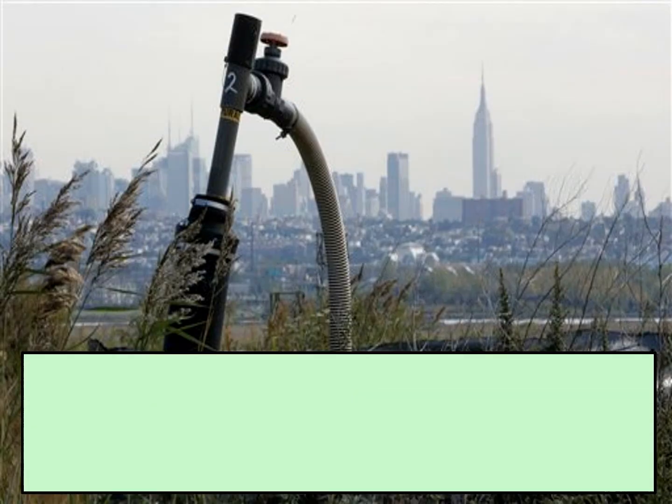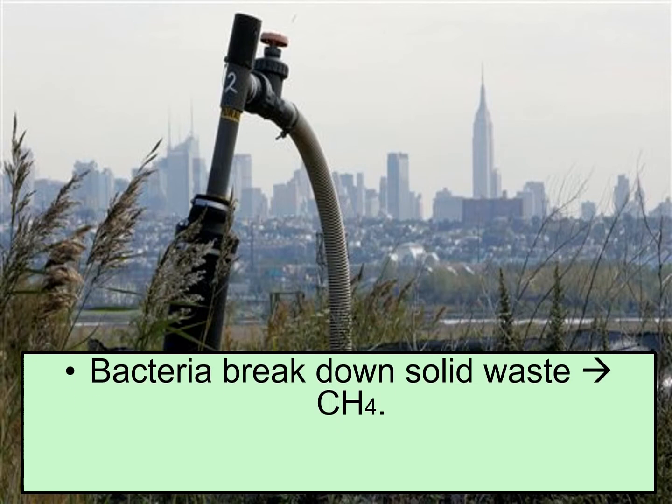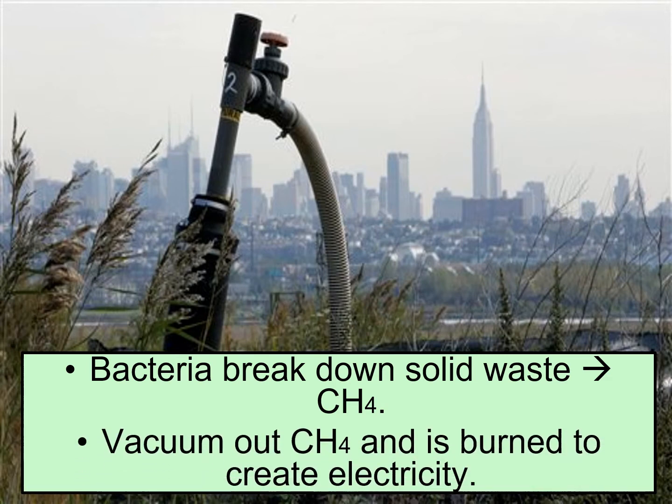A cool thing about sanitary landfills is the bacteria that are in that soil can actually assist in the decomposition of the solid waste. And as they break down that solid waste, they produce methane as a byproduct. So what we've recognized is that you can actually vacuum the methane out of a sanitary landfill and use it for electrical purposes. You can burn it to spin a turbine to generate electricity.